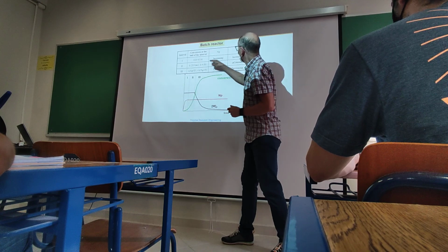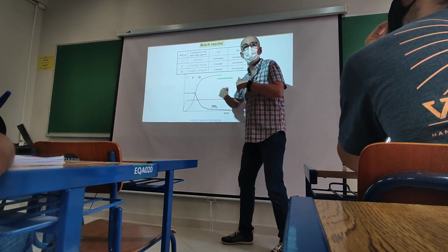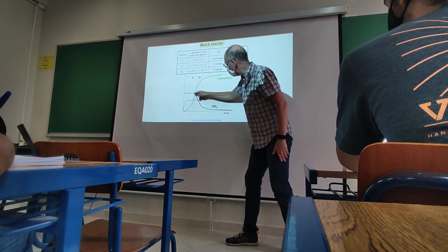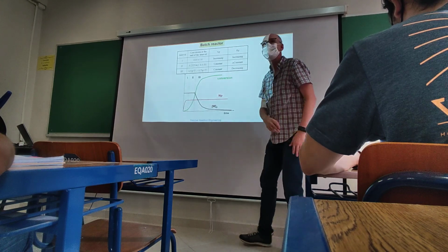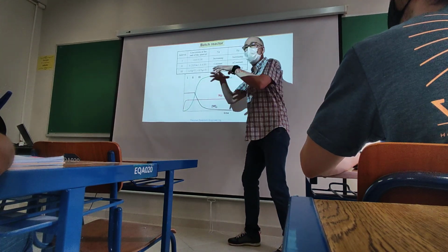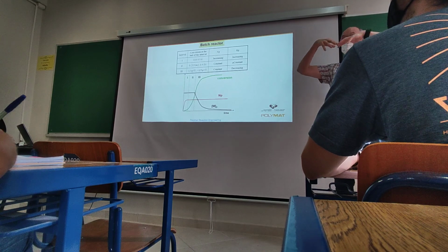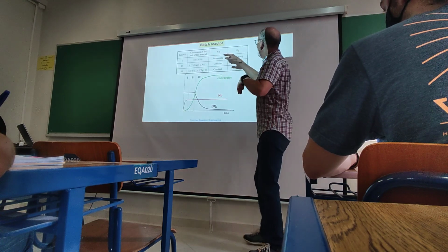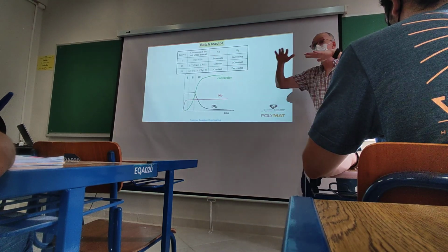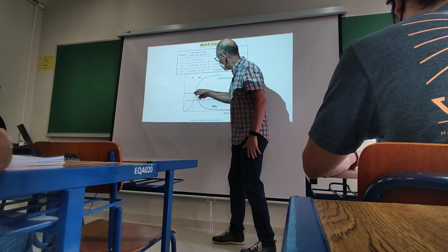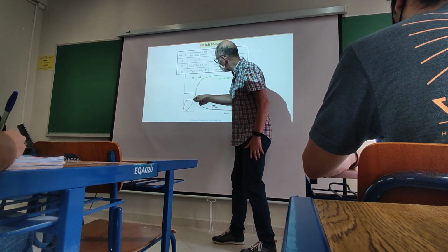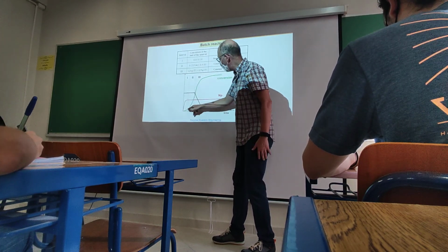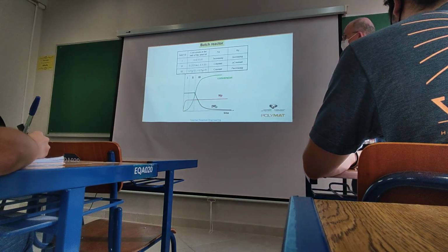In this interval, the number of particles remains constant, no more new particles are generated, and the polymerization rate also remains more or less constant. So the slope here is 1 in the whole interval. Okay? Because the particles are saturated in monomer, the monomer concentration is mostly constant in the polymer particle. And since the number of particles is constant, the polymerization rate is more or less constant. So in this interval, the number of particles is constant, monomer concentration is constant because we are at saturation, we have droplets, and the polymerization rate is also constant.